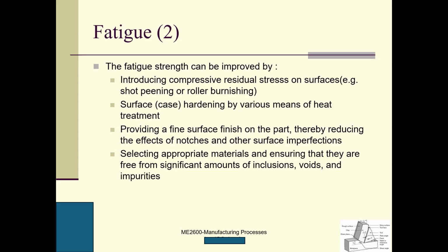And we use the laser beam to heat this workpiece. When the laser interacts with this material, we will have high temperature, right? So the air there will conduct this ionization and also pressure. This generates high pressure, and it will act on this workpiece to induce compressive residual stress.